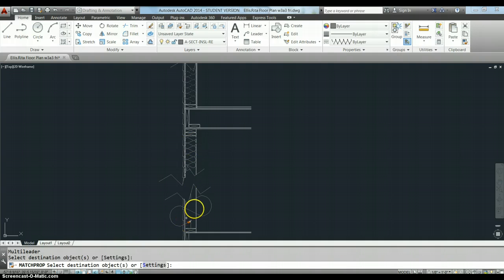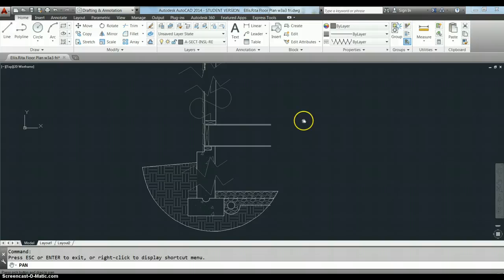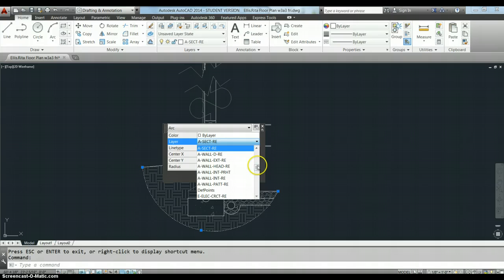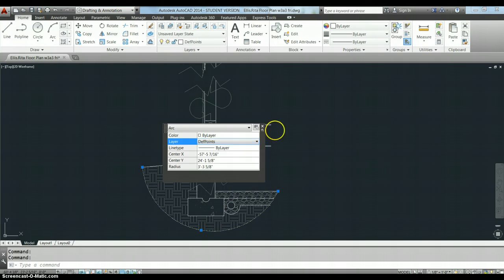Yeah, that looks good. Okay, so you know what to do with this top piece. Go ahead and get your drywall in. Go ahead and get your floor thickness in. Let's keep on going down. This is looking pretty good, as I've said to the others. I like the fact that you cut this out here. As I said to the others, I would either erase this line or I would put it on the def points layer so it does not print. Okay, one or the other.